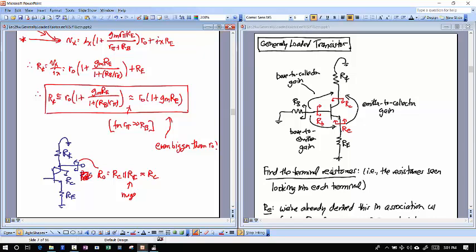Right? You're usually just going to say it's RC, except if I load this with a transistor. So if I did this, put a PMOS on top of this thing, now I have to worry about that resistance going up. Okay? All right, so with that, I guess we'll end the lecture, and I'll see you next time. We'll continue with this next time.